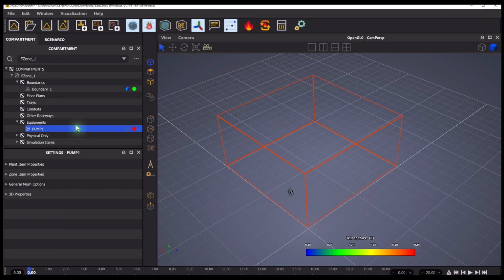In order to make it come into view, you have to get the mouse inside this area here, right next to the red one, which is a wireframe indication of a box. You click on it and drag it all the way into the 3D window and place it over here. Now it places a box by default 1 meter by 1 meter by 1 meter and drops it in the area where you've released the mouse.